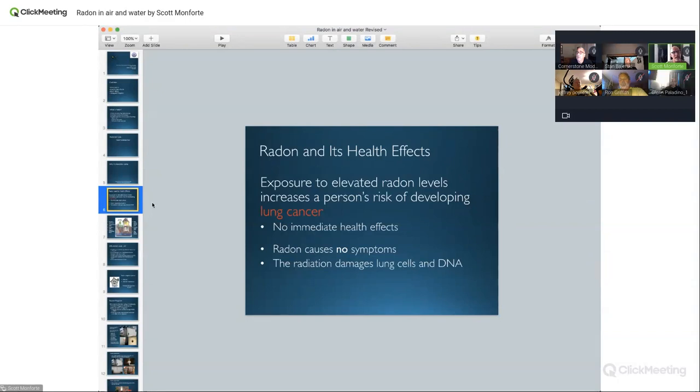If you open the second floor windows, you're right, it could raise the radon, and we tell our clients, hey, if you open the windows, it could make it worse. But how is it making it worse? If the air is going from the basement and up out through those windows, it's creating more negative pressure, so it could elevate the radon levels.